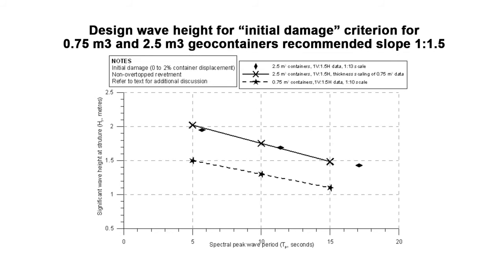A big long-distance swell, say generated down in the Southern Ocean, is typically up around 15 seconds, and can be 20 in some circumstances. So most of the open coast of southeast Queensland and New South Wales is generally in the 10 to 15 second range for wave period, but an enclosed water body is more like 5. So for these design curves, the longer wave period waves are travelling faster and have more energy. That's why these curves fall down for longer wave periods.